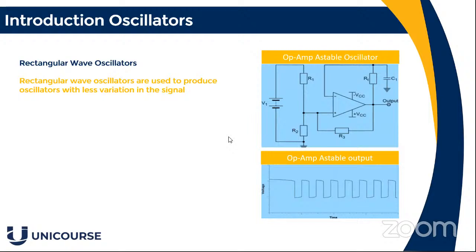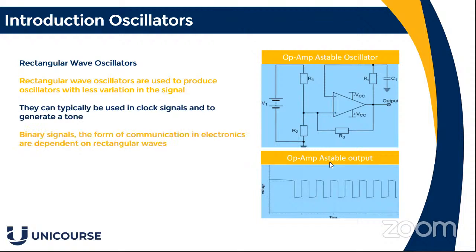Here we're moving on now to using op amps. What was traditionally used some years ago were things like the 741s, as you can see here, with the negative and the positive supply voltage. And here we've got the output, and instead of a sine wave, on this one you can see on the trace that it is a square wave. Depending on the value of the resistance and the capacitor, you get a different frequency. And this will also generate a tone.